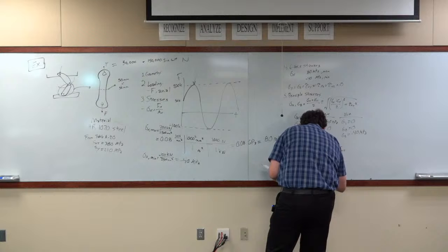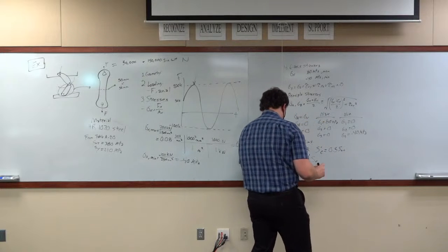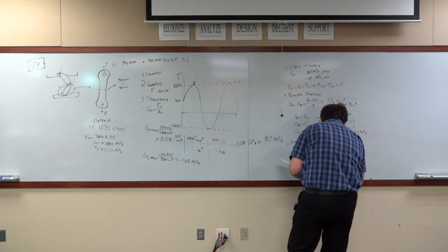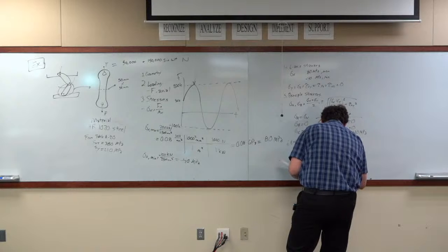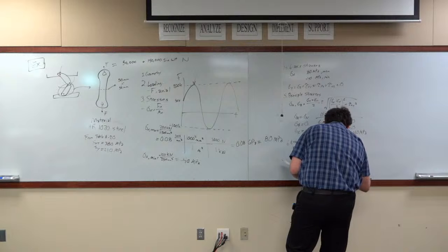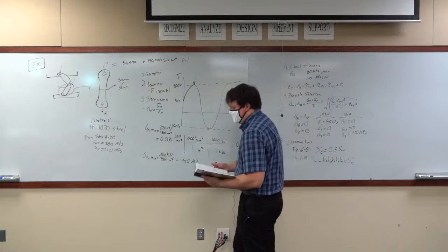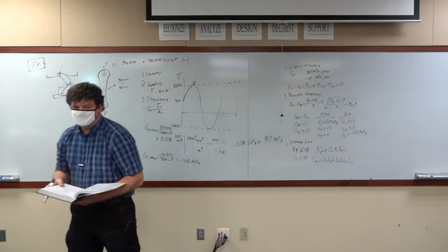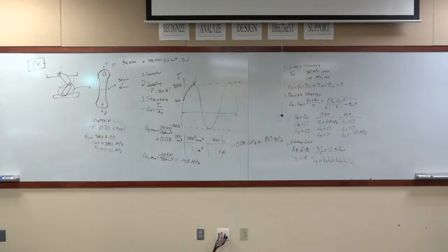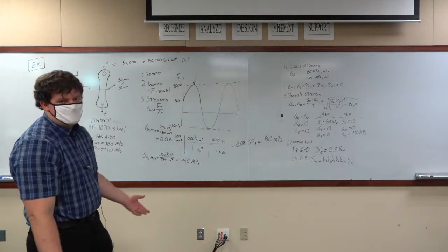And that is the endurance limit, Se, is equal to Ka, Kb, Kc, Kd, Ke, Kf, S prime e. Okay? Again, this is only true for steels. This is not true for aluminums. Aluminums, you usually have to actually look it up on the table.